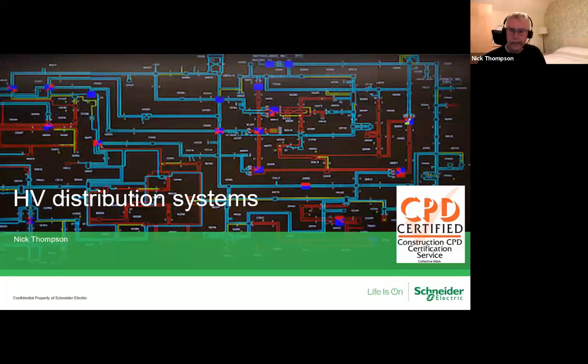And in fact, there is an IEC standard which does detail the various different voltage bands, going right up to ultra high voltage. In the electrical engineering industry, globally, we refer to medium voltage as a voltage band from 1 kV up to 40 kV, and it helps define the switchgear, because the higher the voltage, the switchgear certainly gets a heck of a lot bigger.